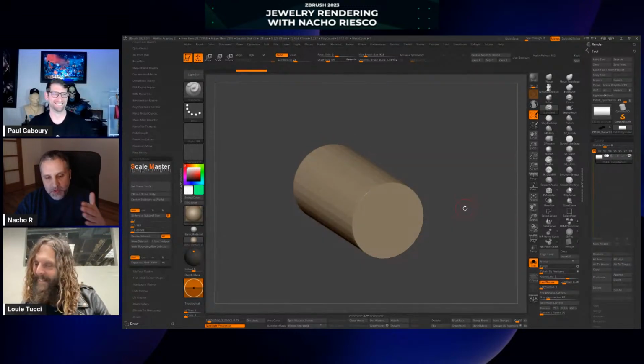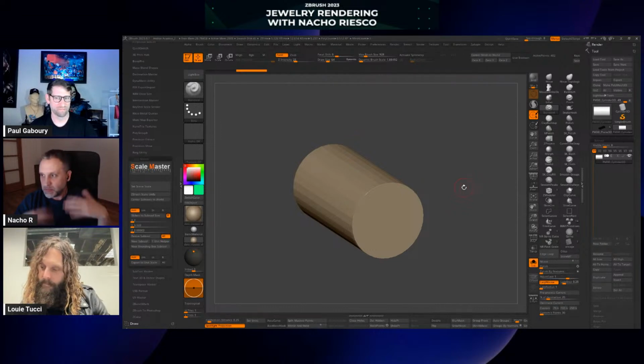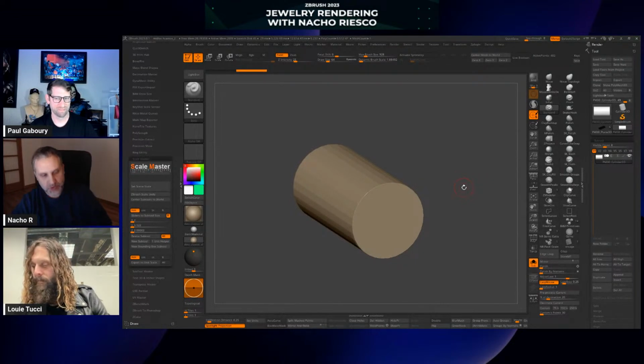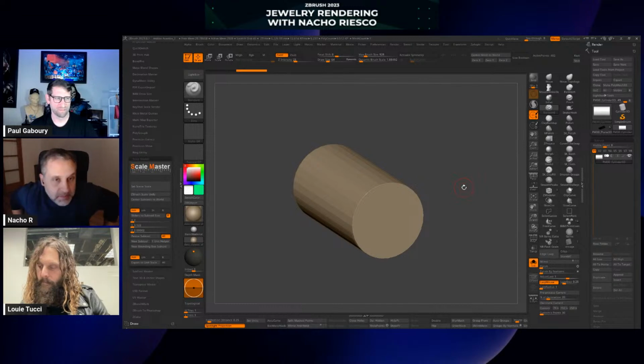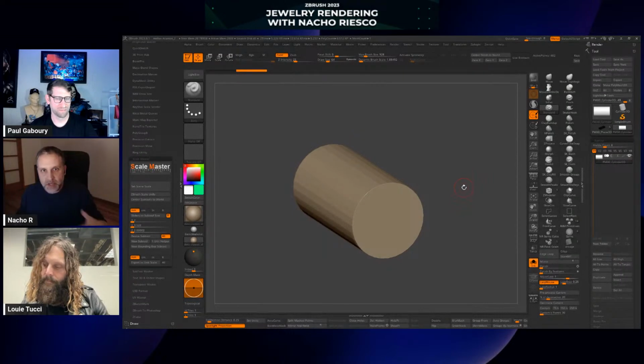Even more important, during the manufacturing process we are losing those measurements. When we are printing the piece, depending on the kind of machine you are using, you can make the piece bigger or smaller, depending on the technology. During the casting process you are going to have some shrinkage on the piece, so you must consider that. Some jewelers want to make it 3% bigger, because they know that with their system it's going to be necessary to have the piece 3% bigger, or 5 or 6.